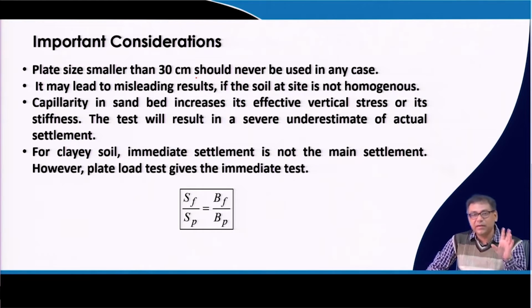So, that means this is very suitable for homogeneous soil. If it is a layered soil, then you have to use this data very cautiously when you are designing the real foundation. And obviously, for clay soil, the immediate settlement is not the main settlement. However, the plate load test is an immediate test, so that means a short term test. Again, to use the data for clay soil, you have to be very cautious.